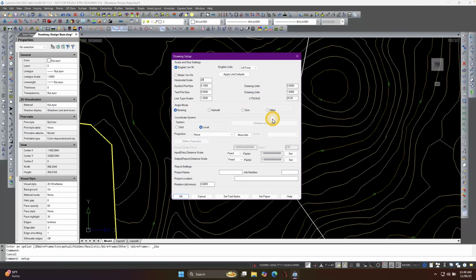You can constantly readjust and reset your line type scale, that LT scale value, to be whatever it needs to be so that when it draws a patterned line, in our case our line type scalar field says 1.25, so that's 1.25 plot units, which would be inches for us, to repeat the symbol, well then it needs to set my global line type scale up to 25 to make that happen.